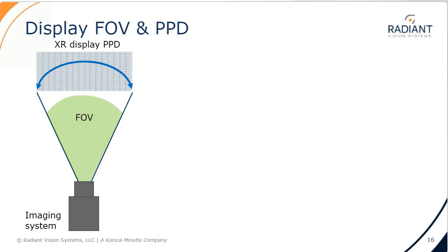Like XR devices, XR display test systems must balance imaging resolution and field of view to increase PPD. If we have lower resolution imaging systems, this means fewer measurement pixels to capture and discern the visual elements of the XR display. This is a bigger problem when capturing larger fields of view. Assuming we are using an imager with the same resolution, the measurement pixels spread over a larger area means fewer pixels per degree can be applied by the imaging system across the display.